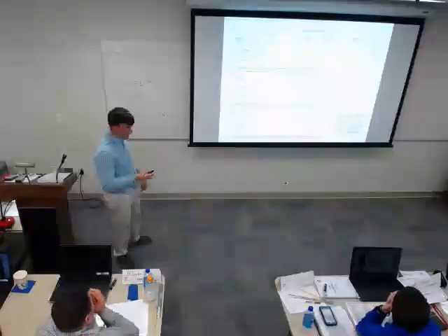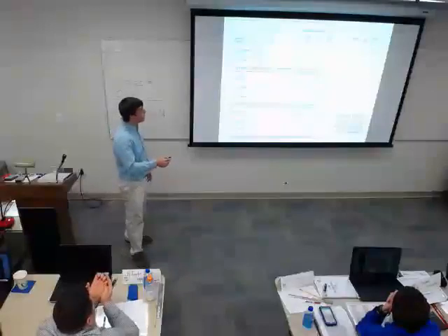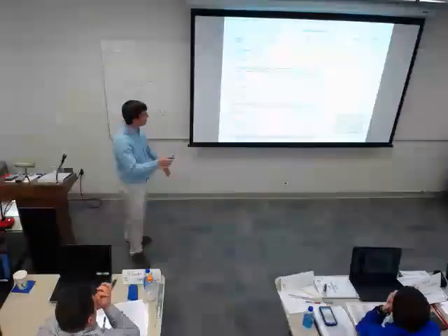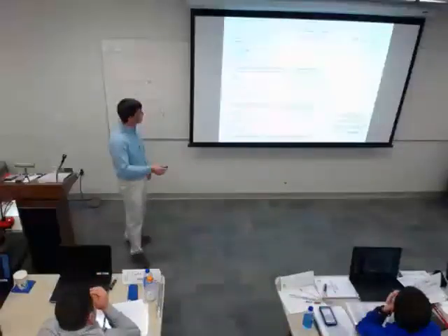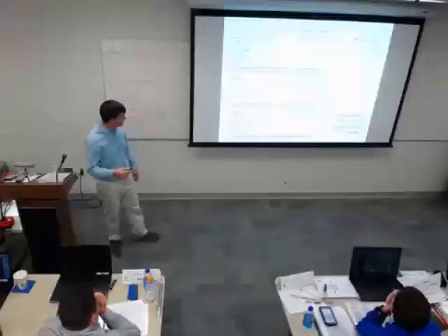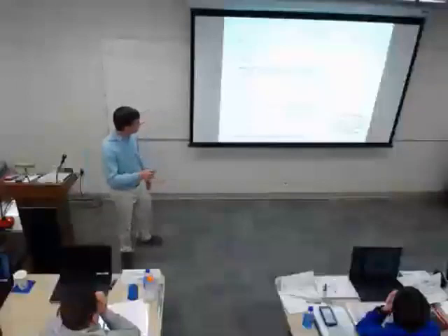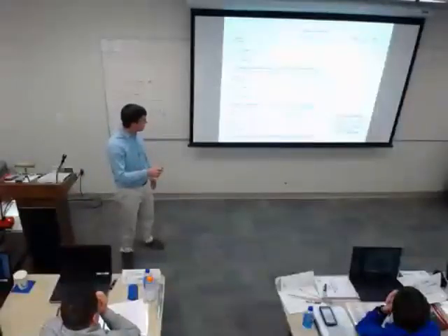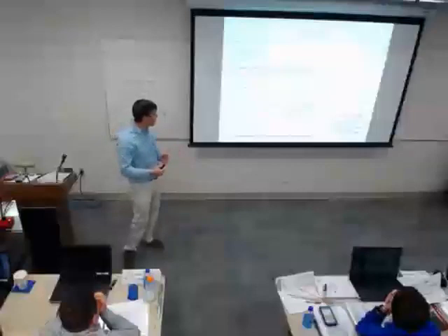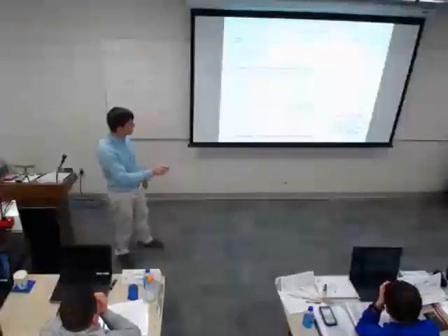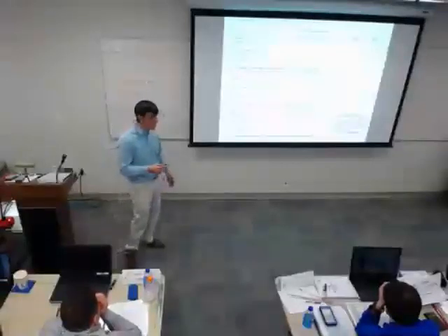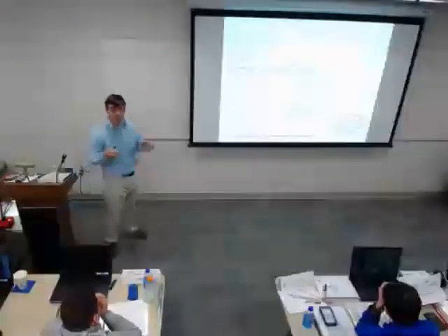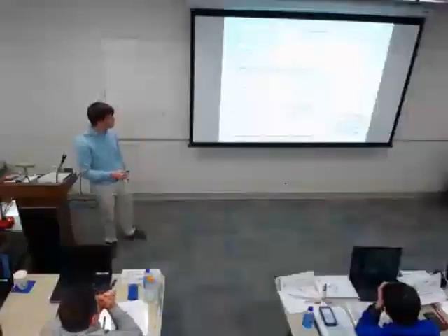Same thing here. All of these are getting better. If you were to look at these, we went from mitered elbows to turned radius elbows. And what is also interesting is that the type of inlet vanes doesn't matter from a system effect standpoint. See, these letters are the same as these letters. So if you had short ones versus long ones, from a system effect standpoint, it doesn't matter. I assume it would matter for whatever the designer is calculating overall, but it's not a consideration for system effect.